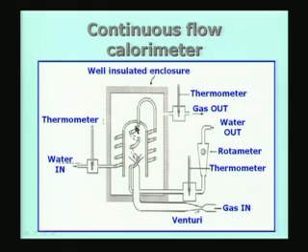the burnt gases are going to be cooled by water which is flowing in the opposite direction. So, the burnt gases are going to go up like this and come down and then probably go out at the exit here. The water which is used to cool the gases is going to enter, and its temperature is measured, its flow rate is measured. As you can see here, it passes through all these tubes which are going to be removing the heat from the burnt gases or the products of combustion, and the water is going to move out through the exit here, whose temperature is again measured.